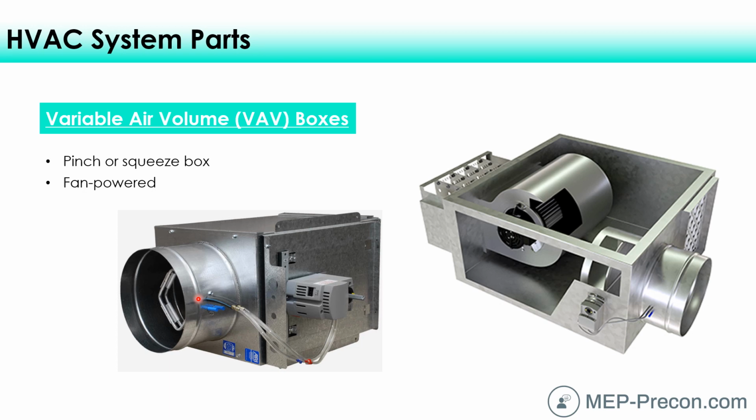As you can imagine, if the air volume changed, that might be a little bit distracting. This at times could be quieter than a fan-powered VAV box, but at least this is constant. You don't notice it changing. So those are just considerations. We talked about giving you considerations between different parts of the mechanical system. So those are some things to think about. We'll talk about this more when we talk about different systems of HVAC.